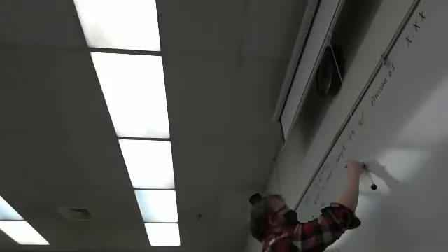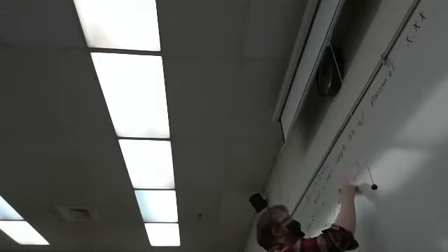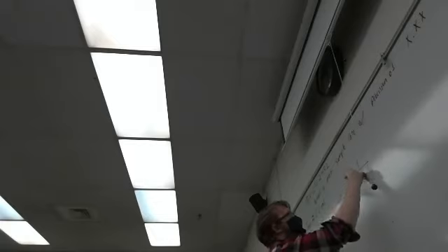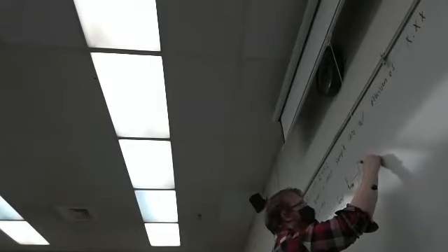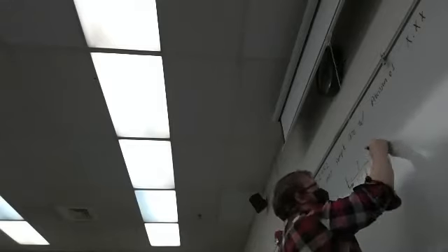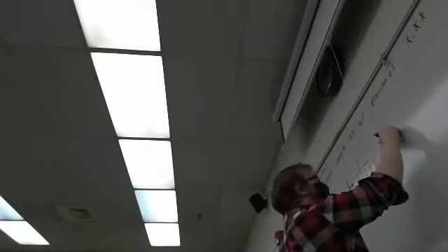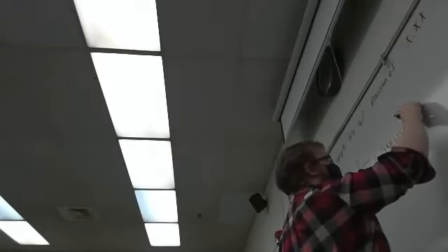So with that, the real one then is f_sample max equal to 1 divided by that 16.6 milliseconds plus 16, because there's 16 bits, times the period, which is 250 for high plus 250 for low nanoseconds.